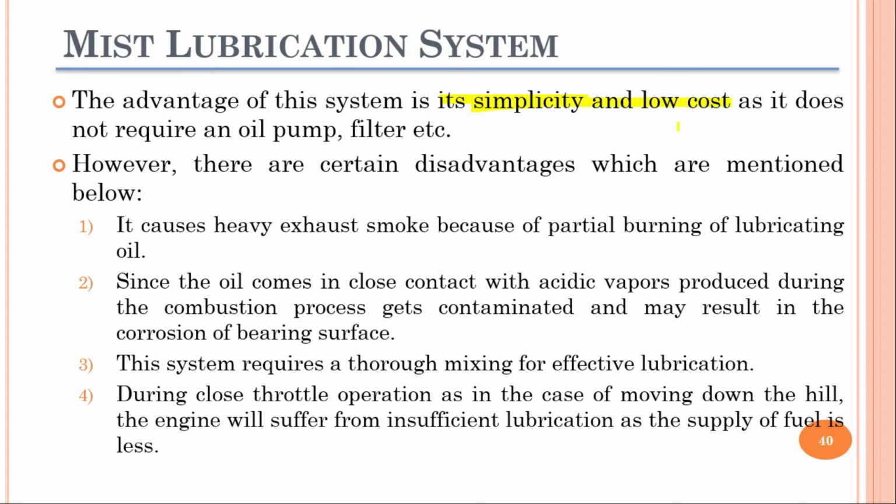But the disadvantages of these systems are far greater. They release heavy exhaust smoke because of the partial burning of the lubrication oil, and since we know that oil is coming in close contact with the combustion products, as a result our lubrication oil gets contaminated and may result in the corrosion of the bearing surfaces as well. This system also requires thorough mixing for effective lubrication, and no one can ensure that the fuel and oil are being mixed thoroughly.